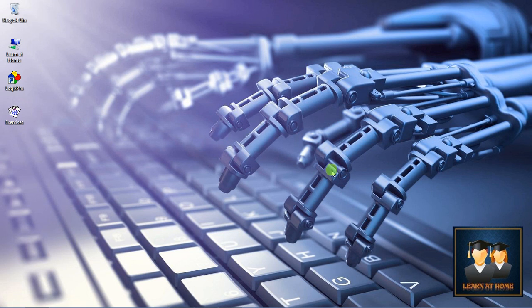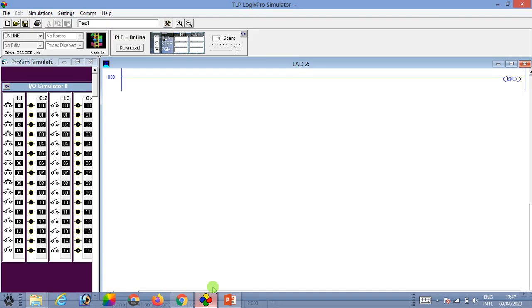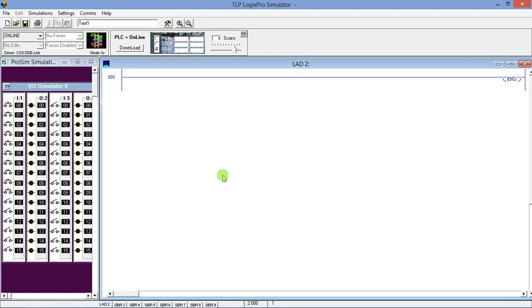In this video, we are going to learn about counters. So let's not waste time and jump to the Logix Pro Simulator. Here, I am going to give you a brief about counters. There are two types of counters available here: up type counter and down type counter.